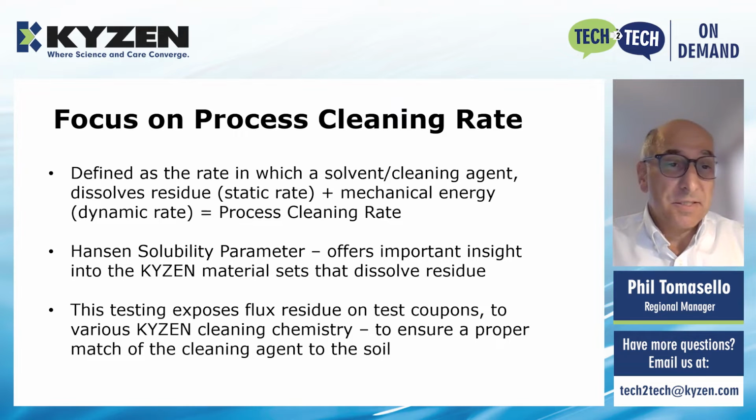Cleaning rate in this sense is really defined by the rate in which a solvent or a cleaning agent dissolves residue. That's the static rate plus the mechanical energy, which is a dynamic rate. That's your process cleaning rate. Using the Hansen solubility parameter gives us insight at our labs here at KaiZen into the material sets that dissolve residue.